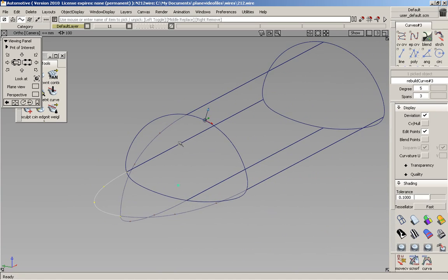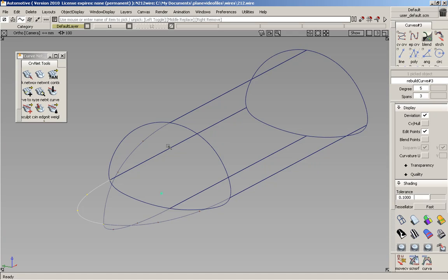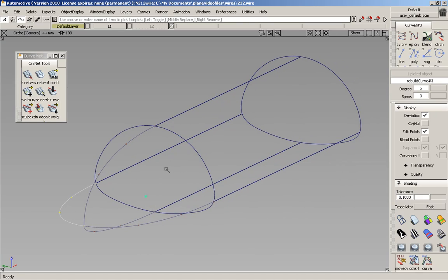So what you can do is you can actually utilize the curve network tool to build a quick curve network in here, and this is great for an on-the-spot surface request or something like that. If you want to come up with a quick surface to show a designer, if you want to just see maybe what a surface would look like with a certain curve network. So if you haven't utilized it before, if you go into your surfaces in your palette, curve networks, this will bring up this curve network tools toolbox here. So we're just going to click on new curve network, and we're just going to select all of our curves.